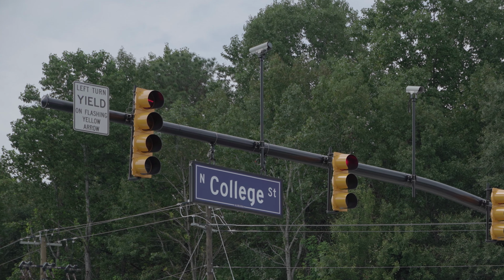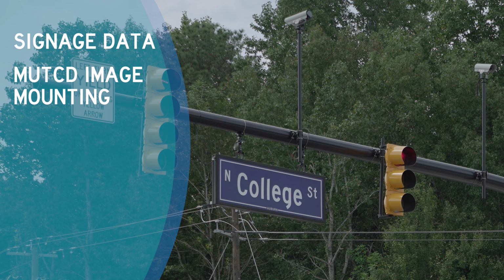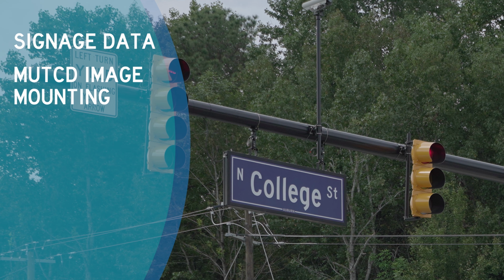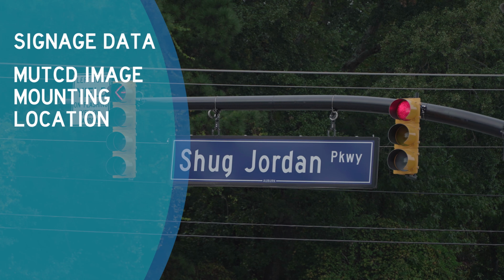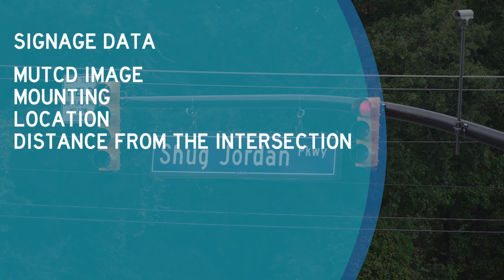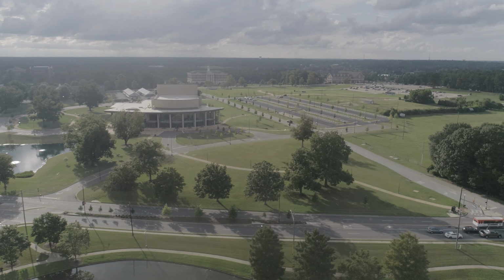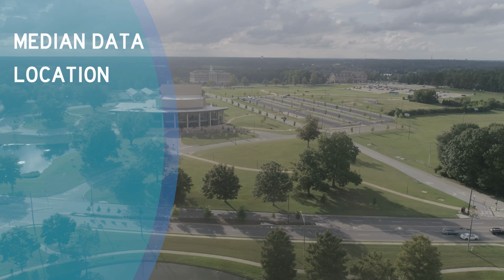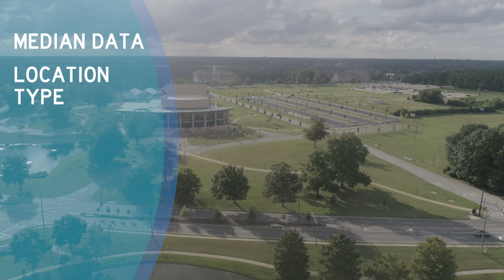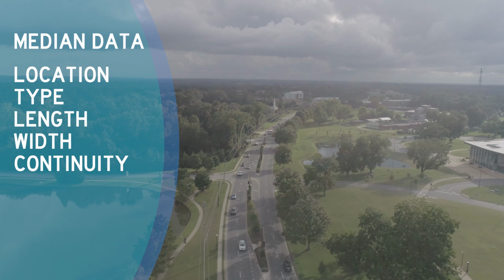Adding or editing signs requires that we first identify the correct MUTCD image, the mounting, whether overhead, pole, or other types, the location such as near side, far side, span wire or mast arm, the distance from the intersection, the installation date, and the manufacture date. To add medians, we will need to know the location of the median, the type such as concrete, grass, or other, the length, width, and if the median is continuous or not.